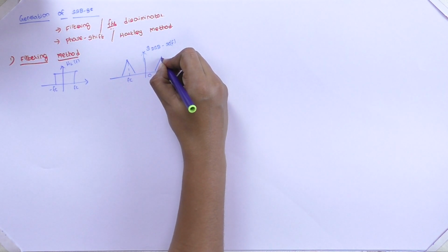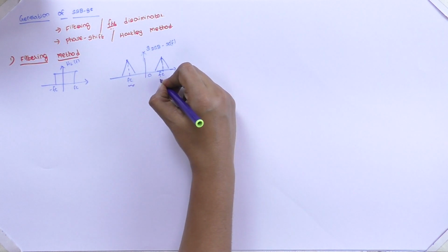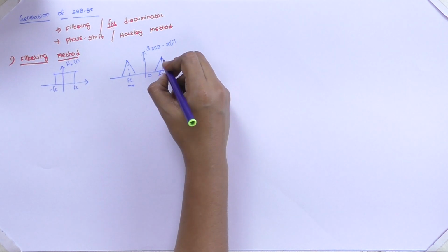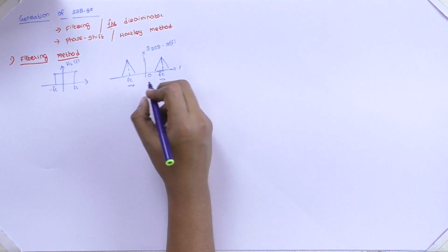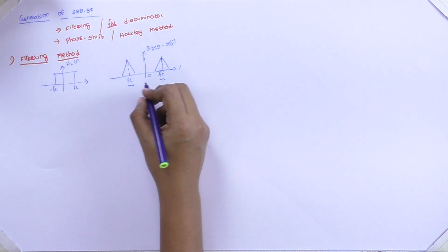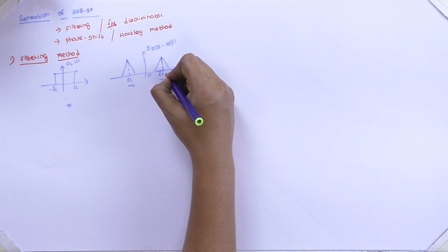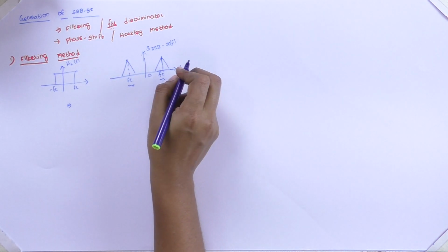Our sideband filter has to cut off exactly at the center frequency of the carrier signal, but practical or physically realizable filters cannot achieve this desired waveform, because practical filters will either pass the undesired portion or attenuate the desired portion.